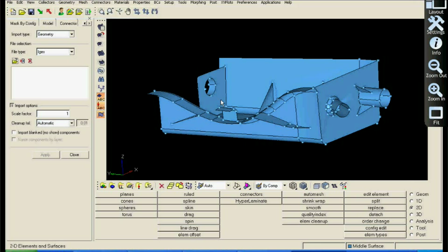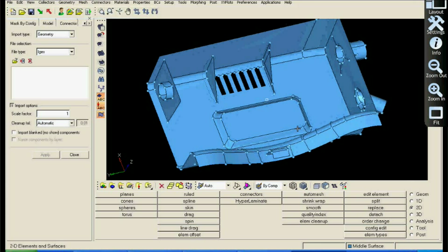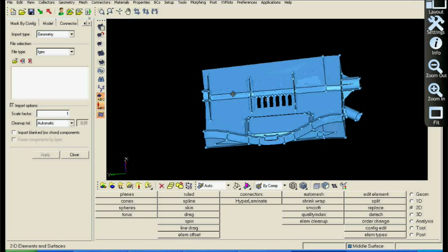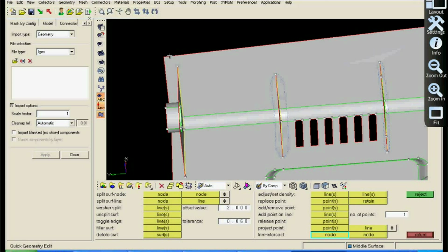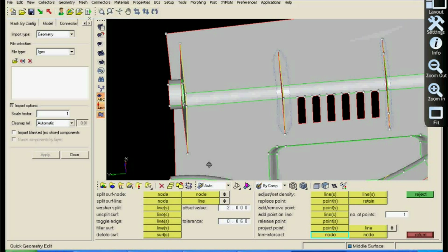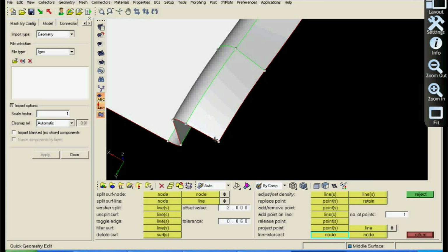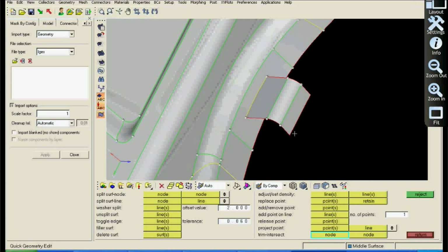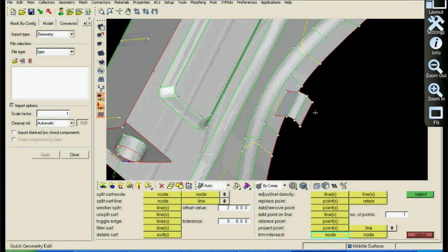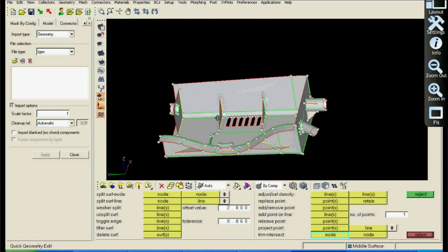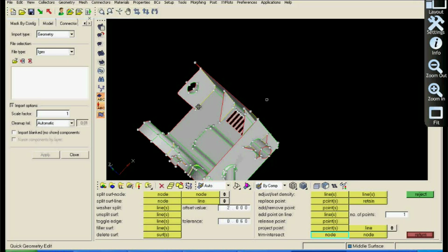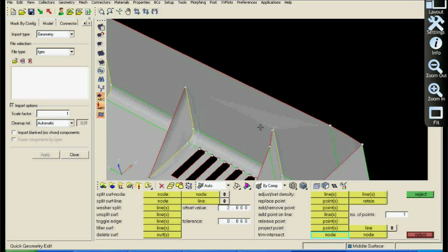Again, I just try to do it with that trim node, and just place a node at the intersection of the lines where we don't have the nodes right now, and we'll try to put some nodes there. Alright, so I think we have. And one more thing I did earlier was creating one more cut and then removing this small portion of the surface.